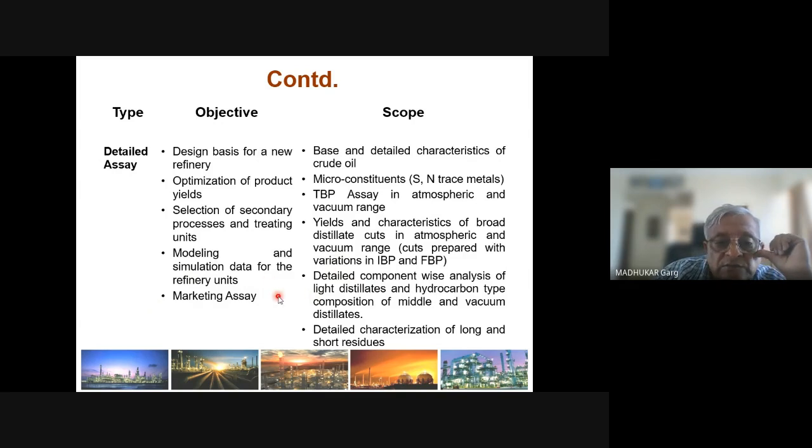And so basically ONGC got the idea and they negotiated that refinery and got higher value for their crude, for that particular crude. So this is how any other refinery which is not making LAB will not actually be able to get value, because it's selling that kerosene as a fuel. But this particular refinery was taking a C9, C13 fraction out of that kerosene and separating out the normal paraffins. And those normal paraffins they then dehydrogenated and alkylated with benzene to make LAB. So the higher the normal paraffins, the more LAB yield they get. Okay, so that is why the value was more.